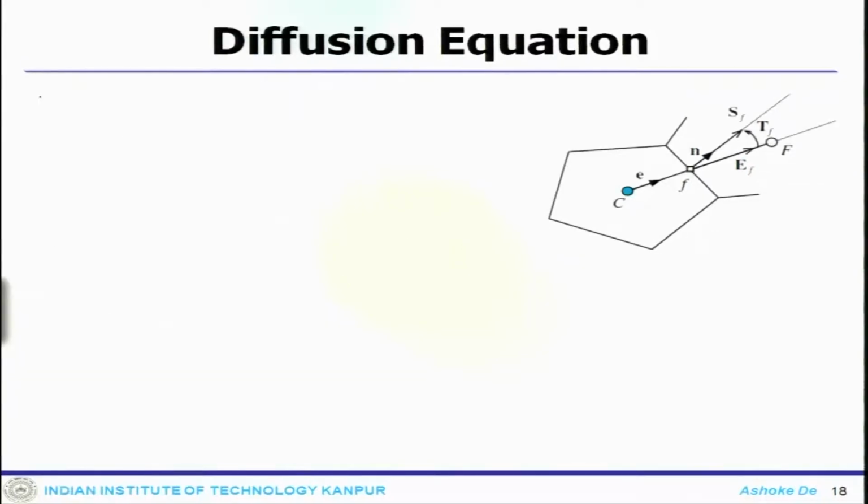Then one can have a second way of doing that, called the orthogonal correction approach. What you do here, again you get these 2 elements connected as usual, and the component of the surface vector, one would be along this line, with angle theta, and the other one would be along the perpendicular line.